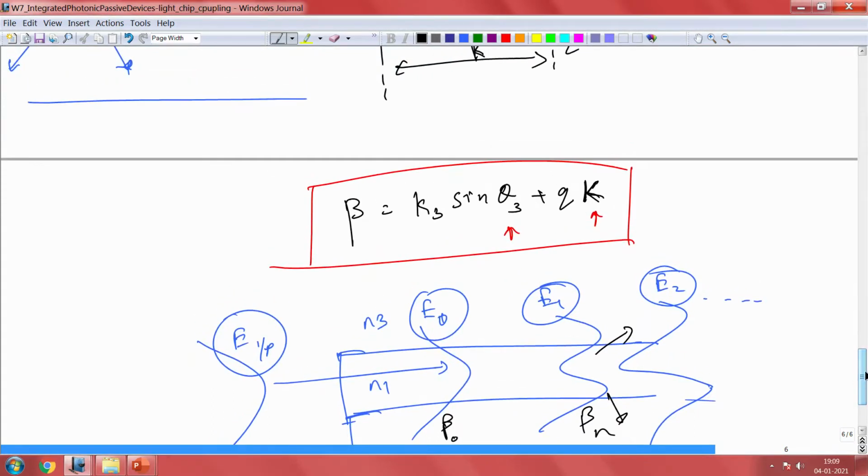With that, we have understood the light coupling problem, which is very important and also challenging. By engineering our surface, you can use surface gratings, and appropriate design would give you good phase matching and reduce loss. The other way to do it is by using a prism, but there are limitations in using a prism, because the prism refractive index should be greater than the thin film refractive index, the waveguide refractive index that you have.